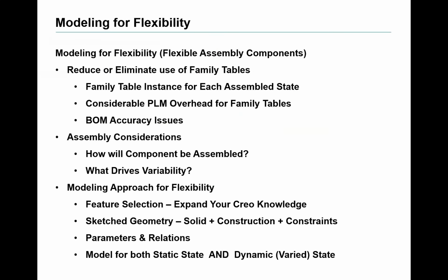So when we think about the reasons for doing this, first and foremost is we're really trying to reduce or even eliminate the use of family tables for these types of components. I've seen customers build a dozen different O-rings of the same O-ring as family table instances just so that they can use them in the assembly. Of course, with a family table, you have all that baggage that comes along with a family table, plus using PLM systems, family tables have a lot of overhead.